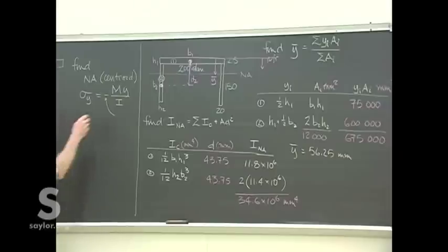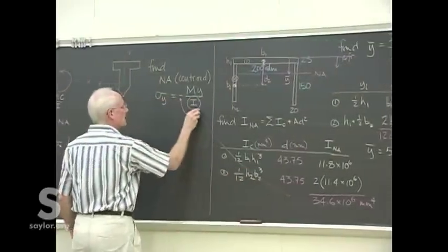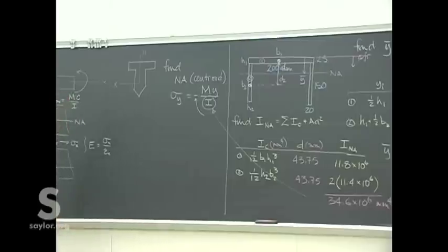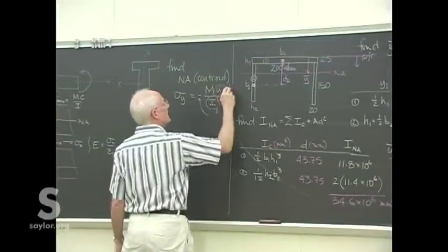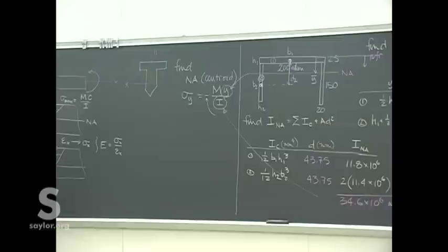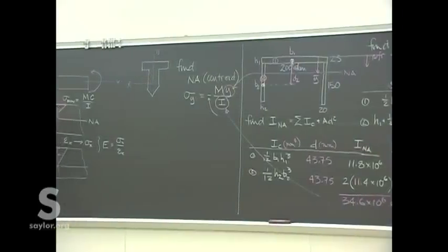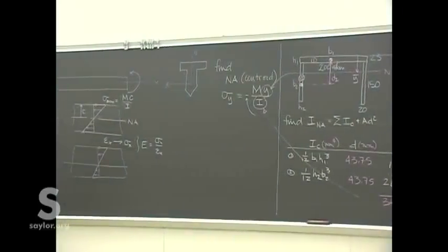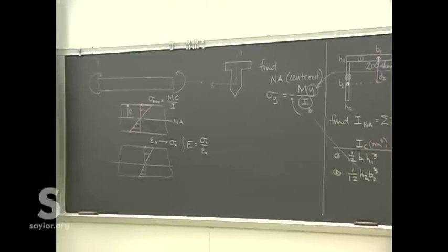And now that gives us the I that goes into there. The Y is measured from the neutral axis. And if we had some given load, then we could figure out the stress at any point across the solid. Does that look a little familiar now that we kind of flew through that in a sort of skeletal way?